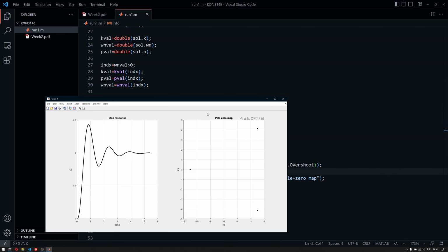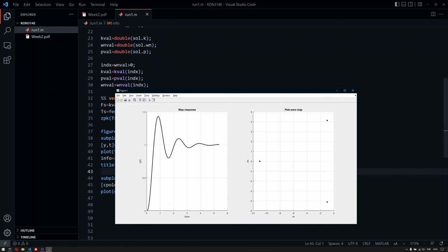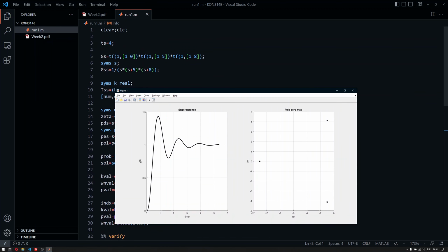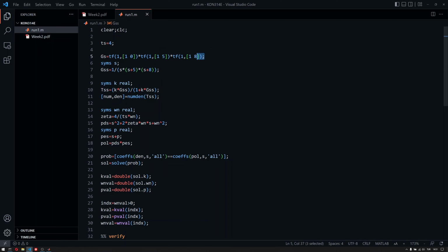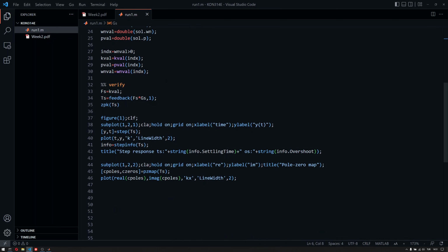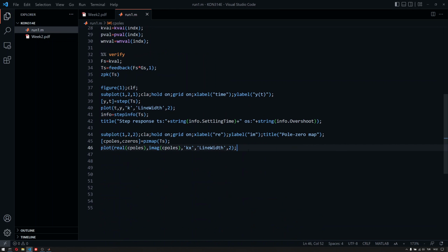By the way, since we are looking for a P-type controller, in the previous lesson we have talked about the root locus plot, and that we can use the root locus plot in order to choose a certain controller, or a certain P-type controller. So what I also can do is the following.